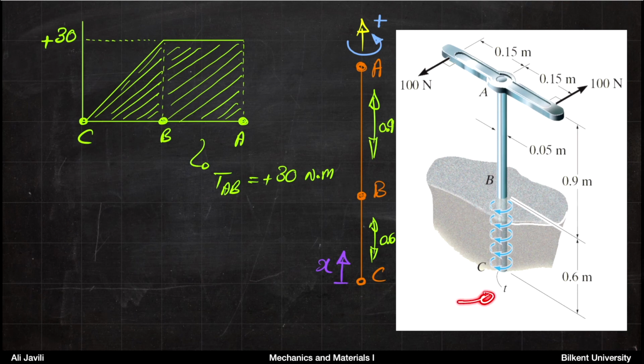And then from B to C, you have a torque distribution, and that is something like torque per meter if you want. So you have that torque distribution t, and that means what you get is an integral of that distributed torque over the length. But also from equilibrium, you know that at the bottom, you have no additional torque to the system.